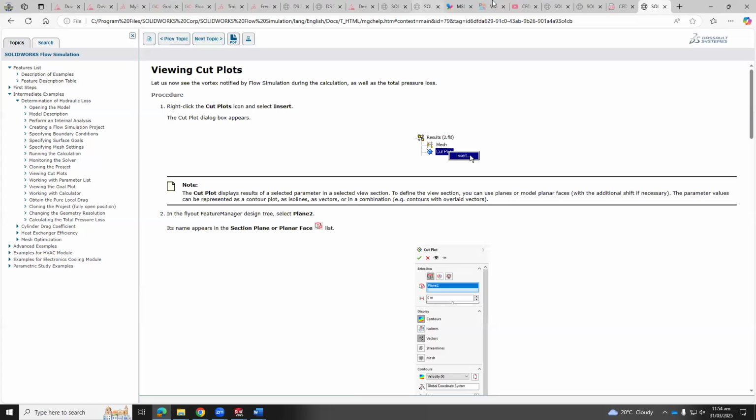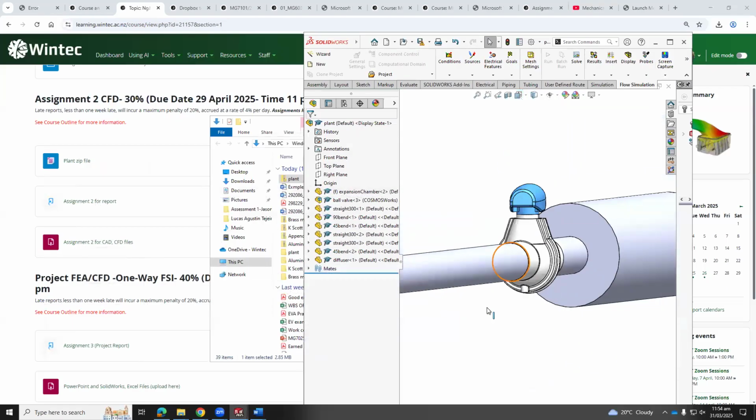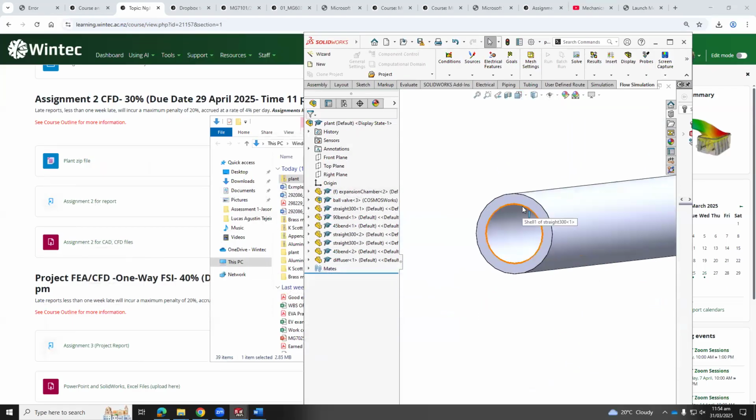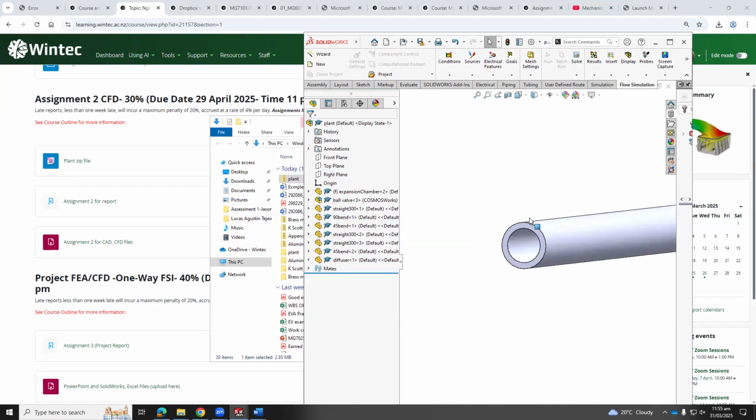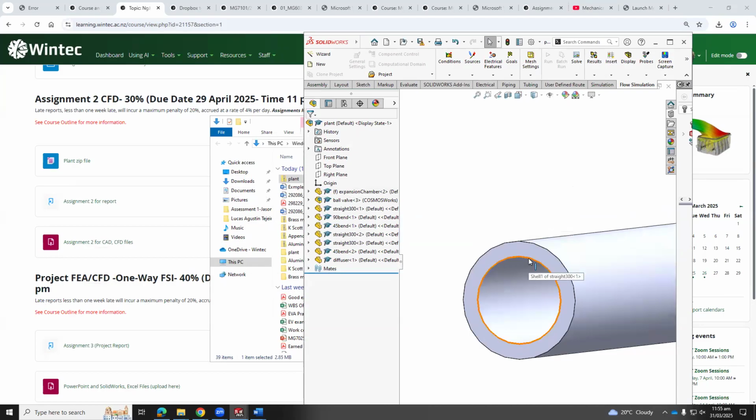You know the diameter. How can I find the diameter? It was given. But if I want to check the diameter, you need that circle. That's your inlet diameter. Reynolds equals what? Rho V D over mu. Rho for water, mu for water are constants. There is a way you can use equations, goals, to calculate even the velocity. So you can use SolidWorks to be the calculator because you don't need to perform that. If you have defined the density and viscosity, it can give you the velocity, the one you want to calculate. So you decide based on that.